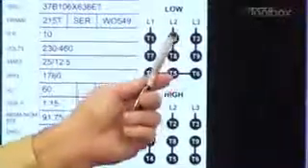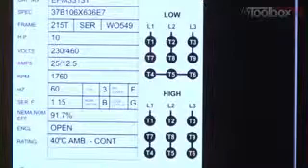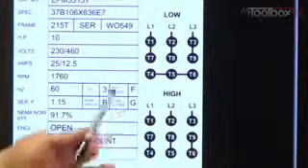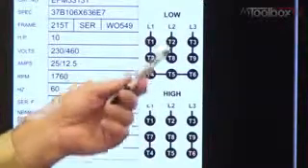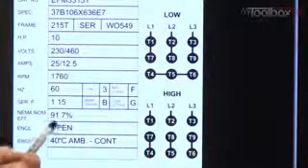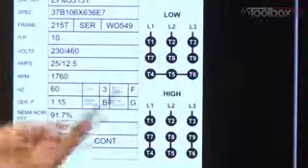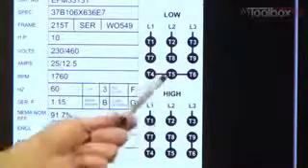The connections for this motor, you'll see there's high and low. This is a standard US 9-lead electric motor. The 9 leads are labeled T1 through T9. By looking at this motor, I can tell that this is a Y-connected motor by the way the connections are made.